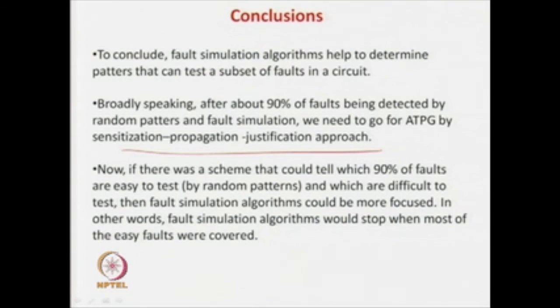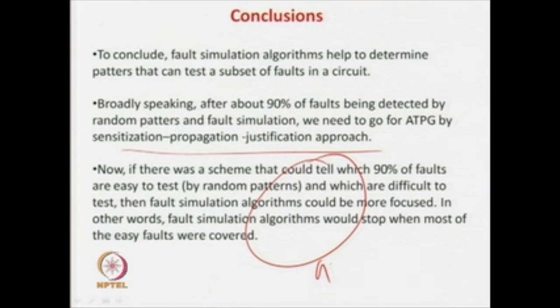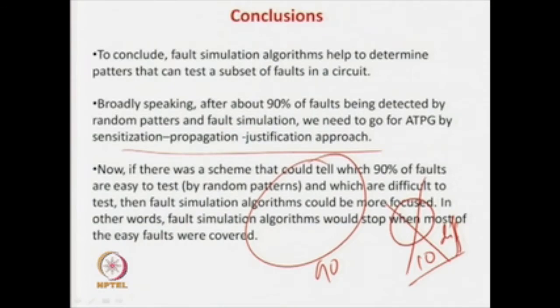So, in the next lecture, we are going to see that if somebody or some algorithm can tell you that these 90% of the faults are easy to test, so apply random patterns for them, and these 10% of the faults are difficult, so do not try for them, that will be very good. At least in fault simulation we will not touch the 10% difficult faults. We will only touch the 90% easy faults.